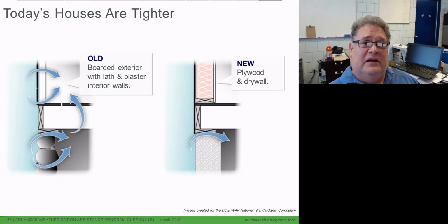When we put the glue in there, we're closing off even more air paths. So what happens is if water gets in the wall, air is not going to move to the outside of the house very easily. In fact, it's going to move to the inside much more easily, and that's where the moisture is going to be carried. A wet wall is going to try and dry to the interior.